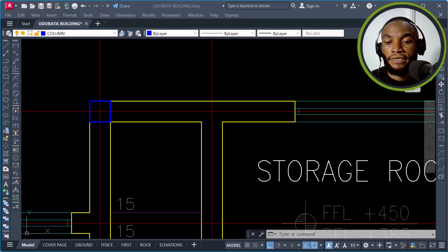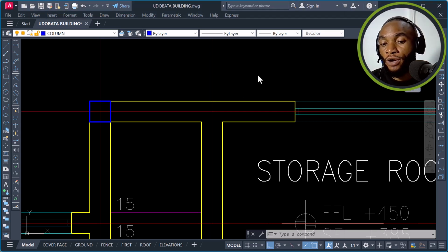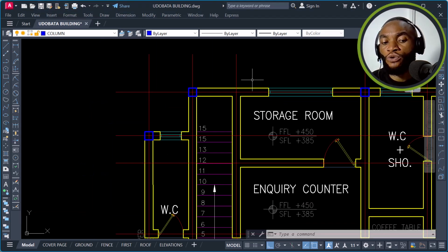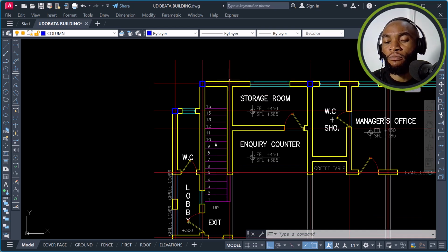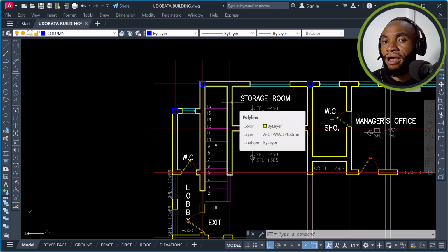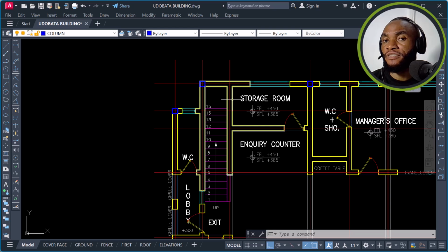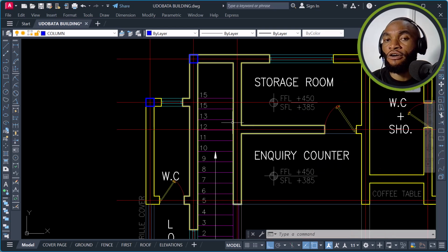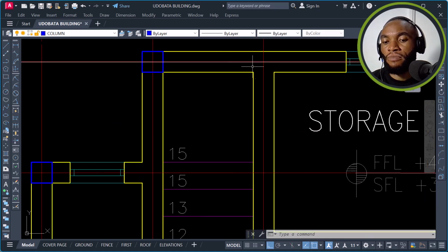It's basically your choice, but there is also a rule in structural design that around your staircase, you should have a column. There are reasons for that, because the staircase on its own is a load exerted on this beam and on these lines of walls.